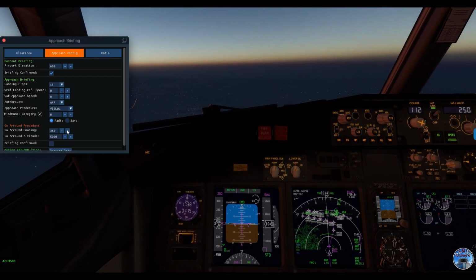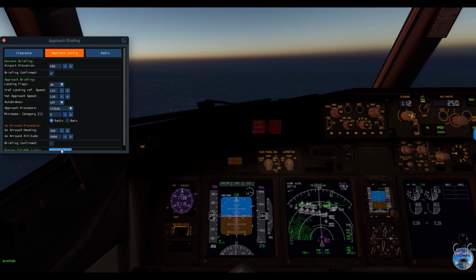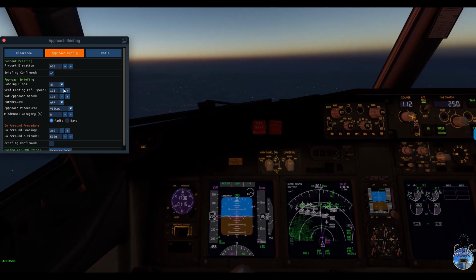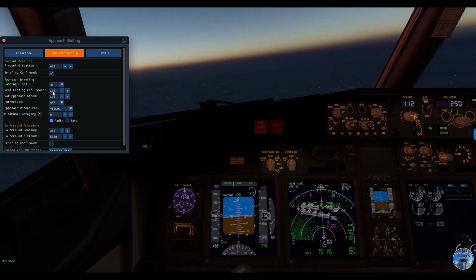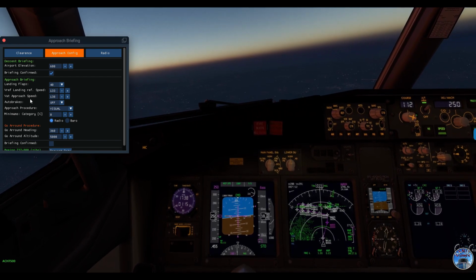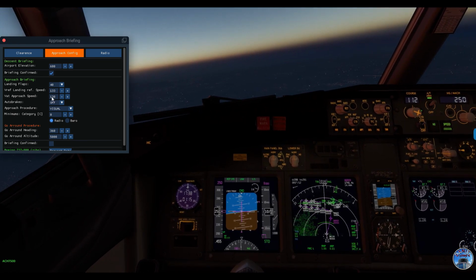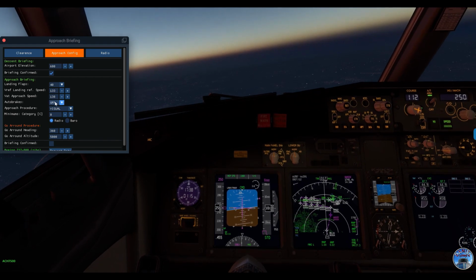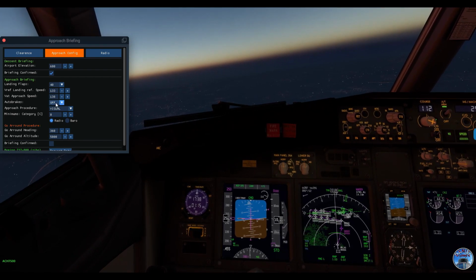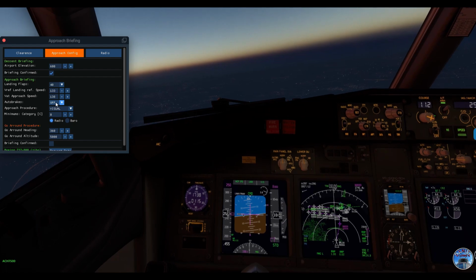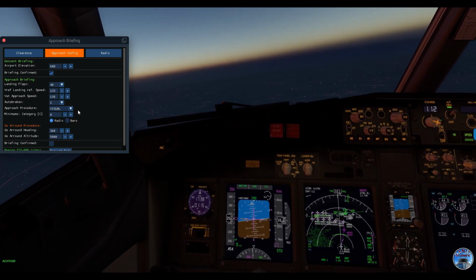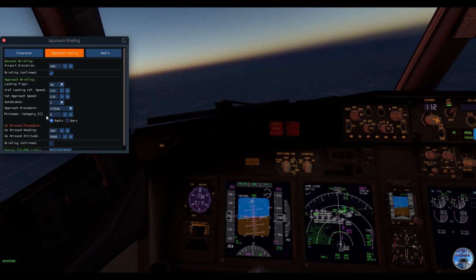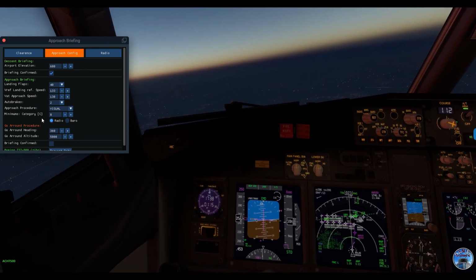Request data from the flight management computer. So flaps 40 we have now entered here. Reference landing speed 133 knots, and the final approach speed is 138. Auto brakes, we will use brake setting 2. The approach procedure is not programmed yet, will come next.